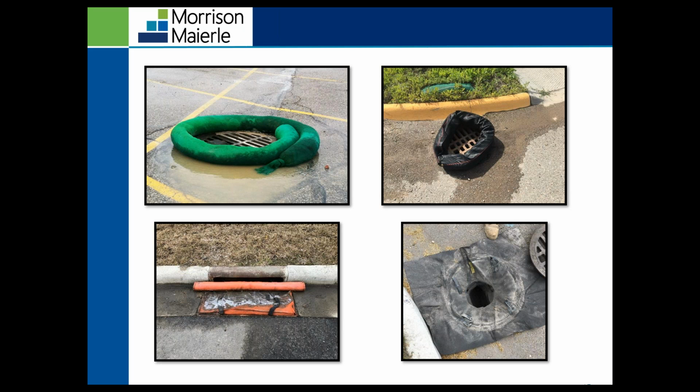I've not used a lot of filter socks before. I've learned from contractors, like say in Bozeman, they are always talking about these filter socks. The BMP on the lower left, the dandy bag, contractors in Billings, they are loving this BMP. The BMP on the right there, that's a photo that I took in Missoula, and that's a BMP that's actually designed to be driven over. It can drive over it. And then there's the witch's hat, which can fit inside that inlet right there.